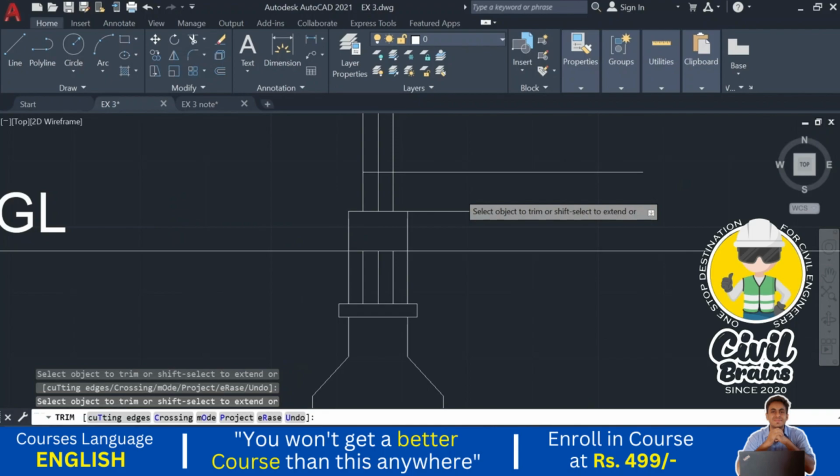If you provide it directly on the ground level, it will not be stable. There is a chance of overturning of the wall, right? So we need to go for the foundation of the wall also. Always remember, in any structure, if it is load bearing, then all the loads will be transferred through the wall only. But in the frame structure, all the load will be transferred through the beams and columns. But for the stability of the wall, to avoid the overturning, to take the self load of the wall, we need to go to a certain depth of the foundation here. We need to provide the foundation for this wall also.